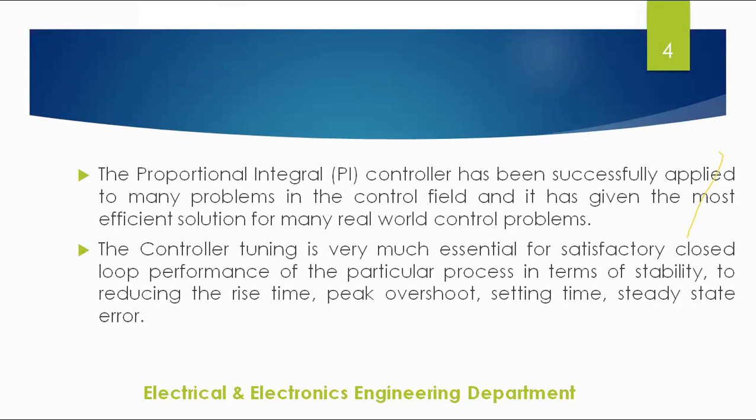Suppose my specifications are phase margin, gain margin, gain crossover frequency, or phase crossover frequency, then we go for the frequency domain. In the frequency domain, we can use the Bode plot technique. Using the Bode plot, we can find out the phase margin, gain margin, gain crossover frequency, and phase crossover frequency, everything.